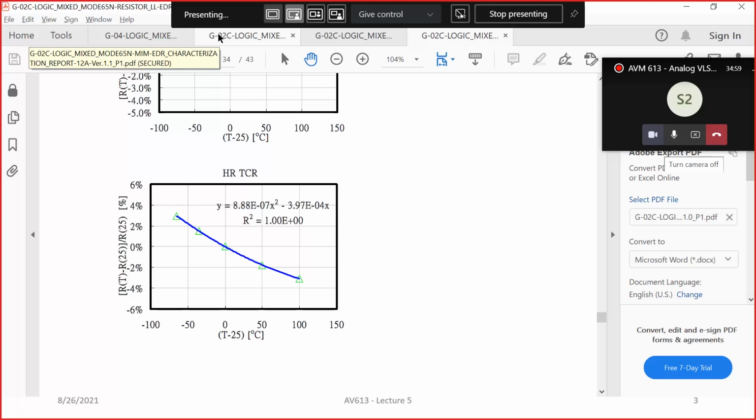Now how to form capacitors on chip? The motivation for putting capacitors, resistors, all these things on chip is, if you don't put them, for every connection of resistor or capacitor, you have to pin out those connections. So if you want to connect a capacitor, you have to have two pins on your chip just to connect the capacitor, another two pins just to connect the resistor.